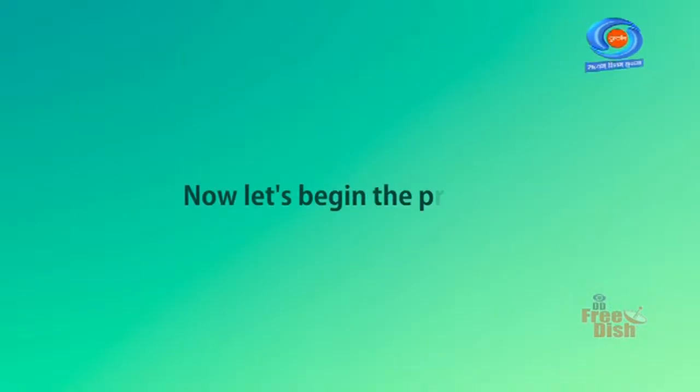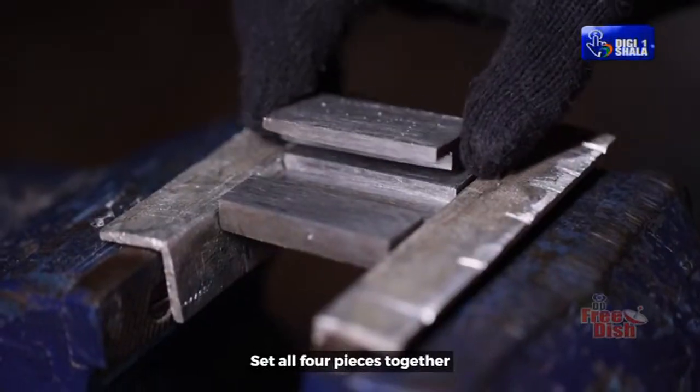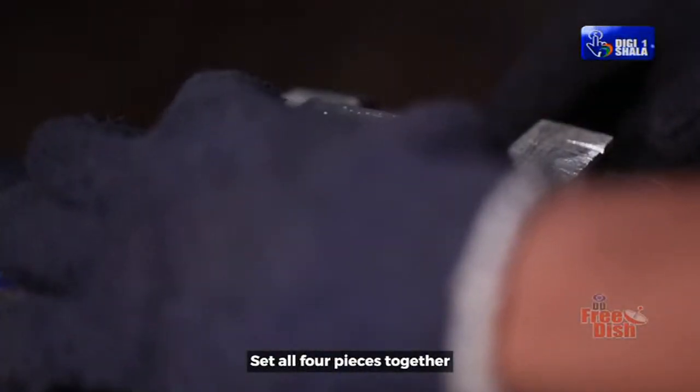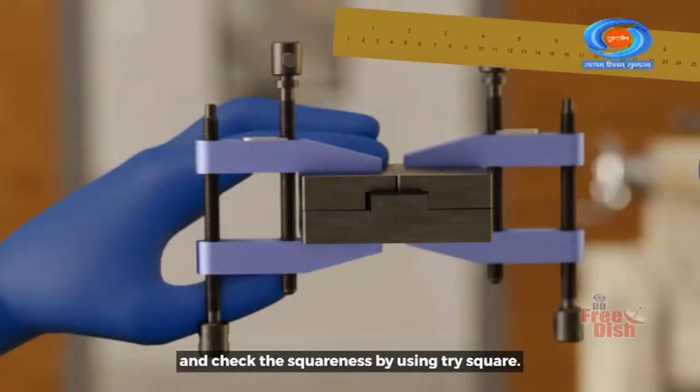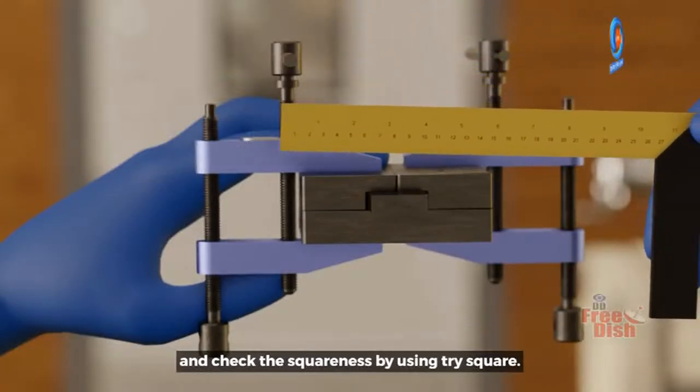File the parts to its size and shape. Now, let's begin the process. Set all 4 pieces together and clamp them with parallel clamps and check the squareness by using tri-square.